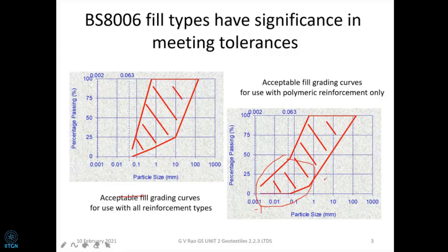So that's an aspect at IIT Gandhinagar we're working upon, alternatives and things like this, trying to develop simpler methods of doing the connection and also trying to simplify the overall fascia thickness if it is possible. But Indian manuals will say that the minimum thickness is going to be 150 to 180 millimeters. So that is an issue which we have to deal with separately.